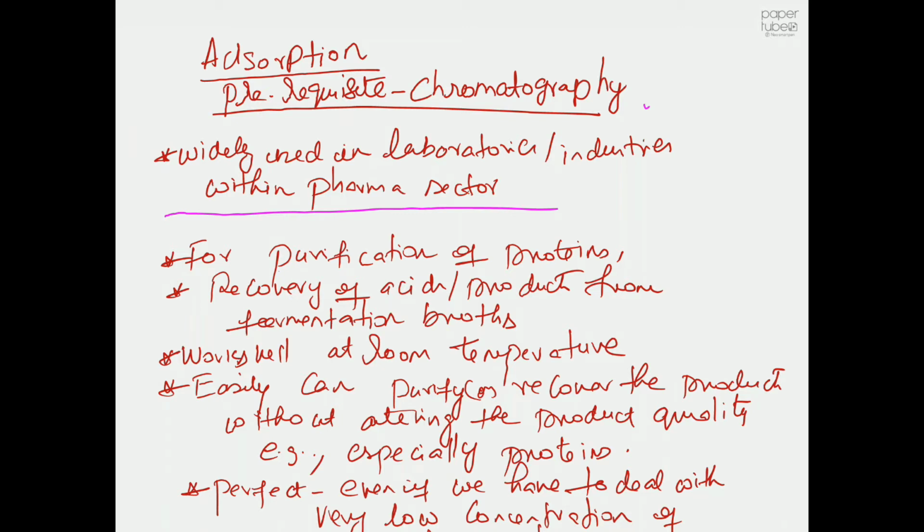I just put some words on where it is widely used. It's mostly used in purification of proteins. Another good thing about adsorption is, imagine you have a protein dissolved in your fermentation broth and you want to remove it. We can't go for other techniques, for example heating the solvent and taking the product out, because if your protein is sensitive to temperature, it will get denatured, lose its original structure, and won't do its job anymore.